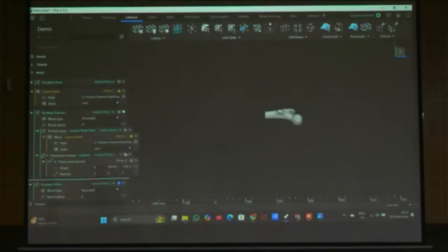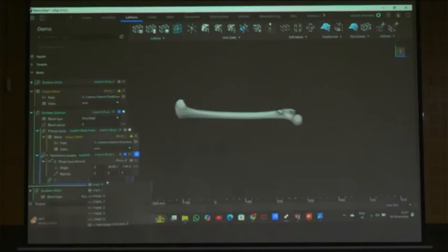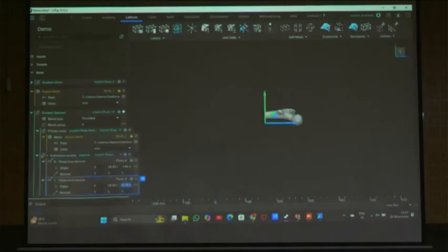We will see. So one more plane I will take. This is the implicit body. See, this side is removed and I need to remove from this side also. So we will take one more plane from normal, or otherwise I will copy the same plane, Control C, Control V. See, this symbol is the toggle visibility. So this plane I will drag here.